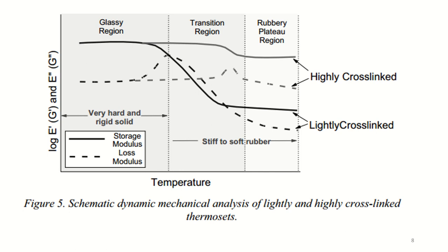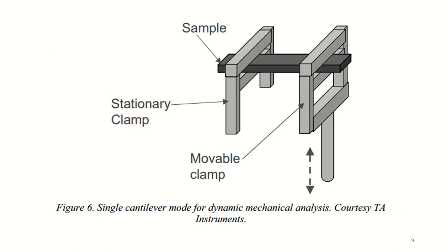For fixed frequency, dynamic mechanical analysis may be performed in single cantilever, dual cantilever, 3-point bend, tensile, or shear sandwich deformation modes. Two illustrations are shown below.